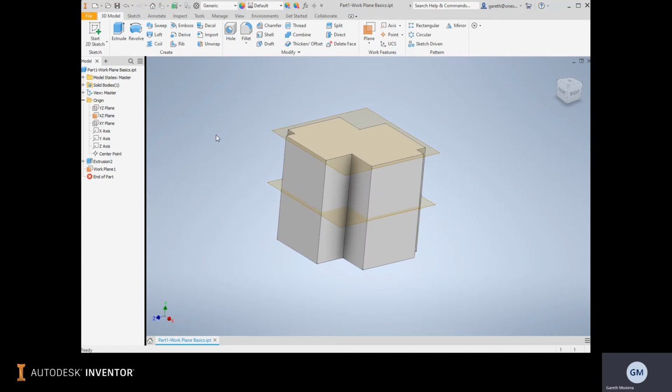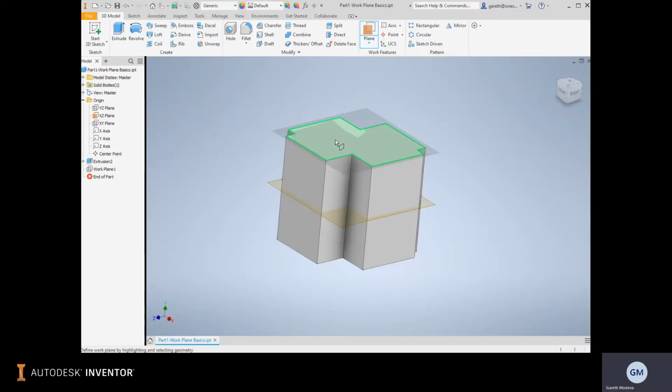So we're going to select a point along the top of that plane, and that'll generate a flat plane. But my previous example was I wanted 1/4 from that. So another way to use the plane tool, I'm going to turn it off, is we'll select the plane tool, and in the background I'm going to click and drag down the direction I want to go in. It creates an offset. That offset must be the total length divided by 4, because that's essentially 1/4. So if this was 40, that would be 10. At the moment, it's on 20 total length.